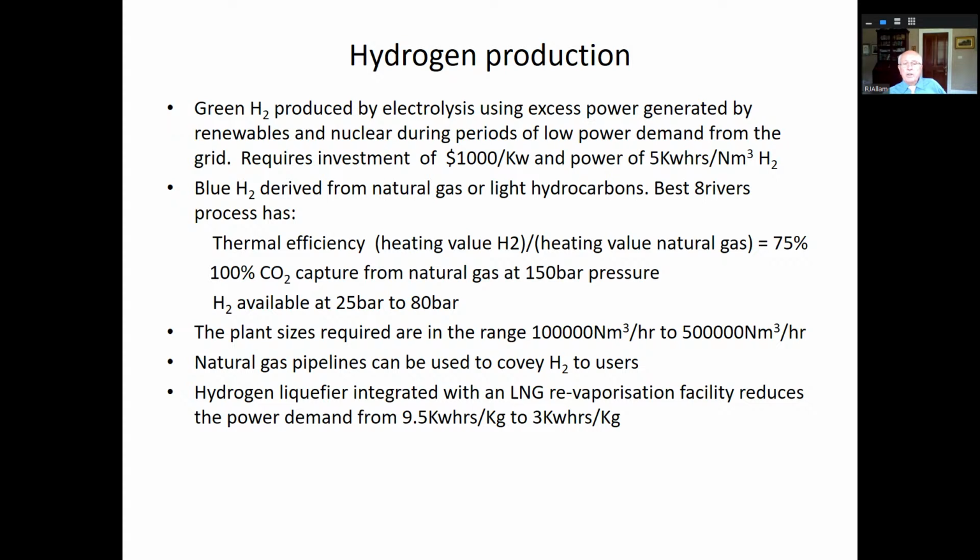It produces the CO2 at 150 bars pressure, and the hydrogen is available at 25 bars to 80 bars pressure. And the thermal efficiency, which is the heating value of the hydrogen over the heating value of the total natural gas required, is about 75%. And it will have a relatively low capital cost. And I think this is going to be one of the choices for new hydrogen capacity worldwide.